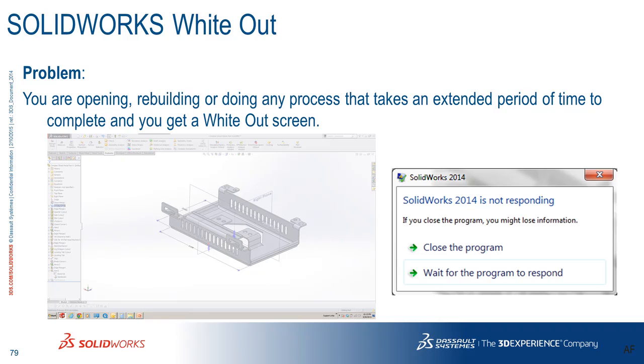Not responding does not mean crashed. Not responding means SolidWorks is thinking. It's a good idea at this point to right-click in the menu bar, get the Task Manager up, and see if the SolidWorks item is pulling processor. Because if it's thinking, the last thing you want to do is stop it. It's just taking longer than you would have expected.